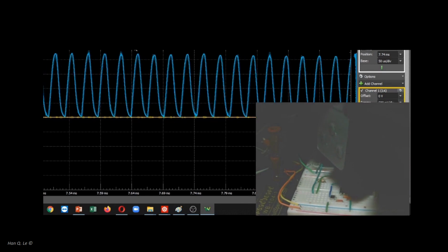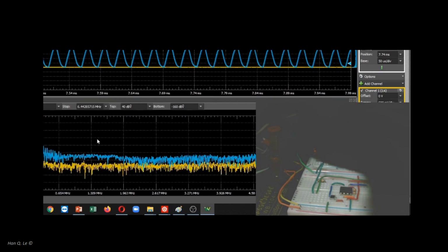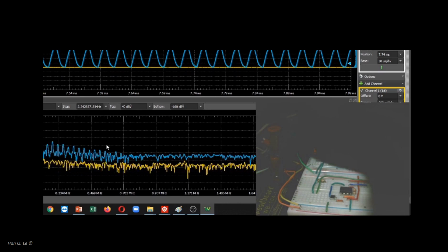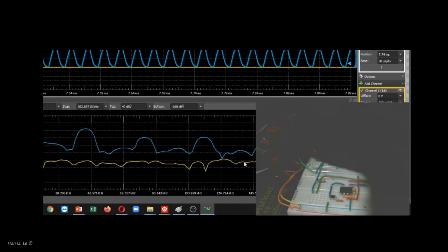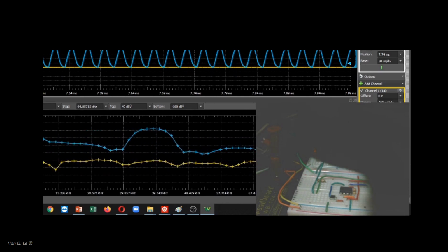The carrier wave with 100% modulation depth was captured. Then Fourier transform was applied to show that the modulation frequency is 38 kHz. This is the special pitch that the appliance tunes in, listening only to light pulses with 38 kHz modulation, and tunes out all other interference lights.